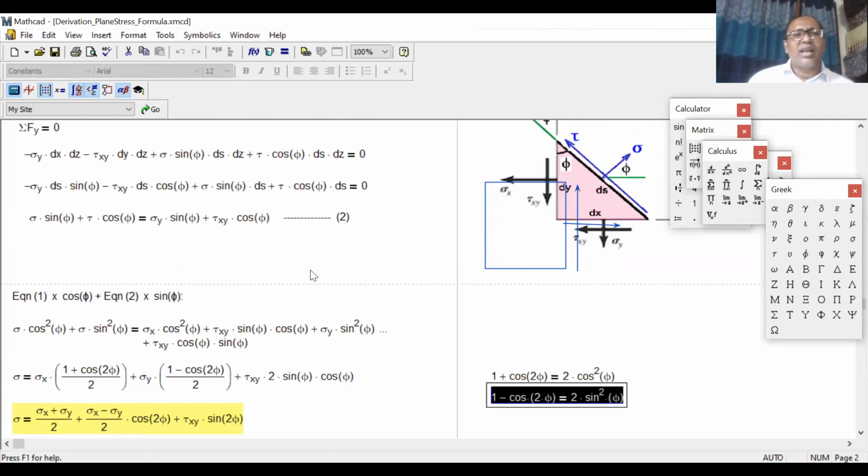Okay. And the other thing you need to remember is that we are making the summation of force, not the stress. So how do we get the force? Stress into area. Now in the free body, we are not showing the thickness, right? Del y is the distance along the y-axis.